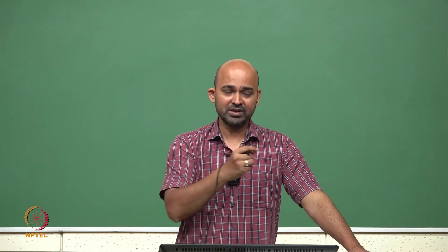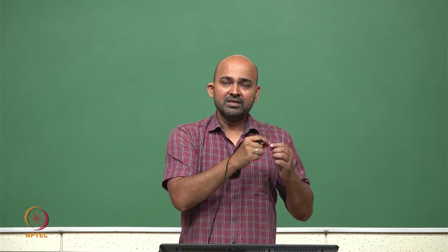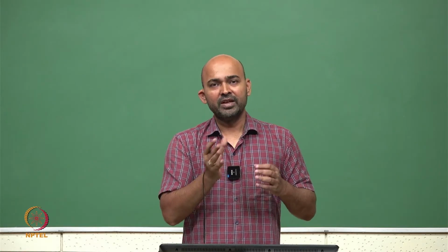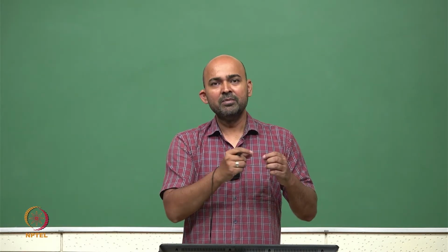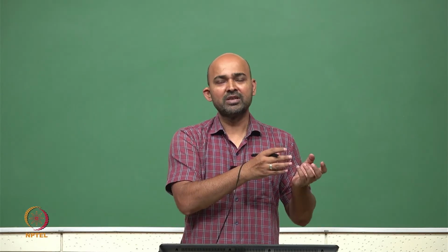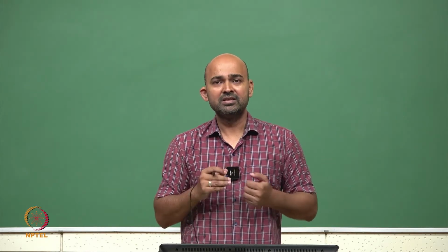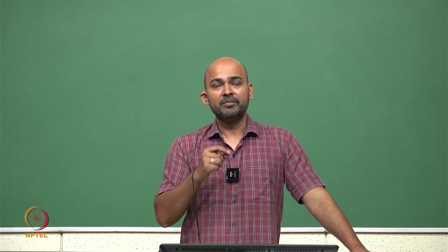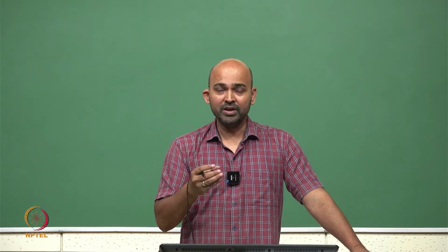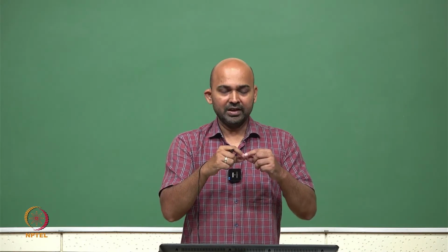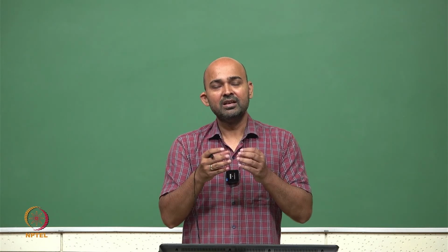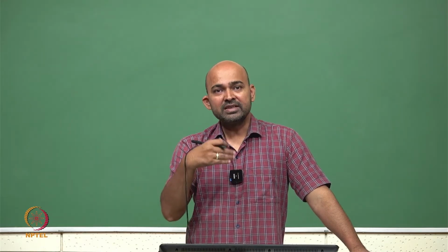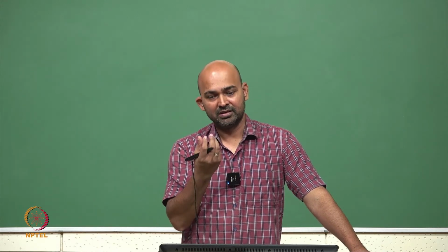The next thing is the trace design. When we design these traces in digital design, if it is not a very high frequency design, we can have a minimum size of trace width and whatever signal we apply at the near end reaches the far end. But in RF PCB, the width of these traces needs to be determined very carefully, because the signal we feed into these traces is not seen as a lumped component.